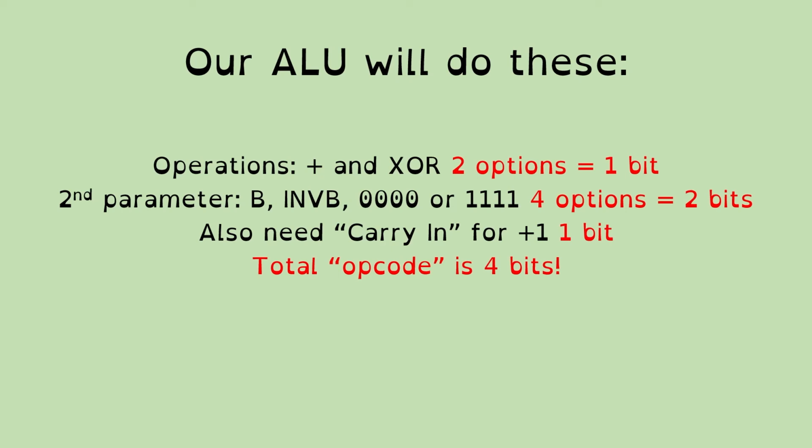And very importantly, we're going to need an opcode to say stop running. So a halt opcode. So actually, we're only going to use 6 out of our potential 16 opcodes which the CPU will understand. Only 6 of them will be things where the ALU actually does anything for us.